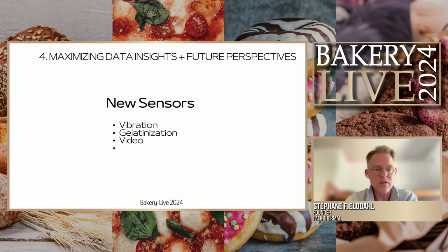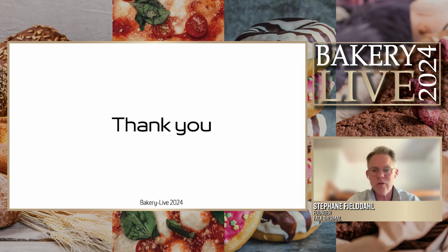There are also technologies to measure the gelatinization of starch, to know exactly what temperature starch is transforming, which can also be another dimension added to thermal profiling. And why not video? And not only video that analyzes the color and the shapes. There are some nice algorithms that go much deeper and probably can open up unprecedented resources in this area. So this is a very quick overview of thermal profiling.